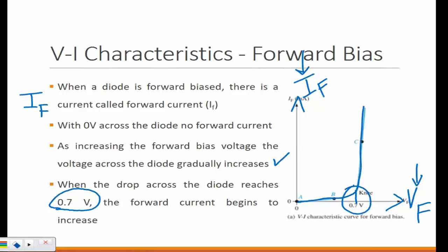So once the voltage on the diode reaches approximately 0.7 volts, the current will drastically increase to whatever the capability of the circuit is. But until that, you see current is not zero. It's extremely small. That's why we say it's not an appreciable amount of current, because it's very small.